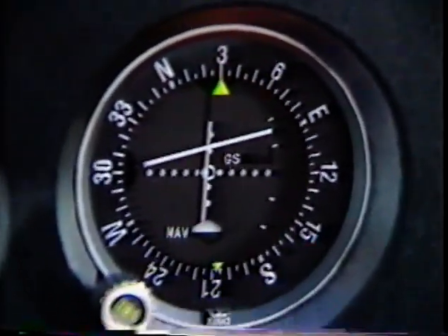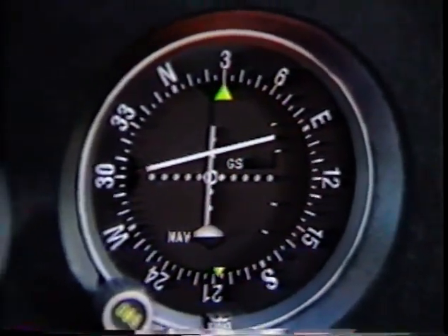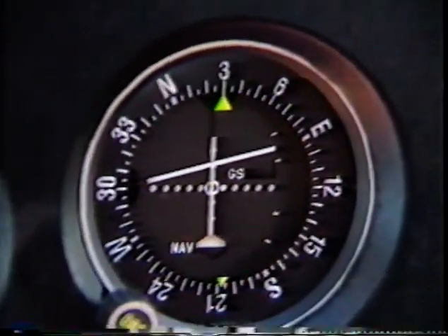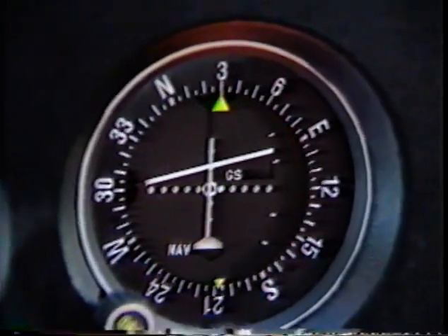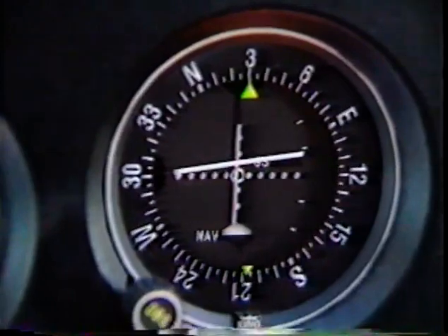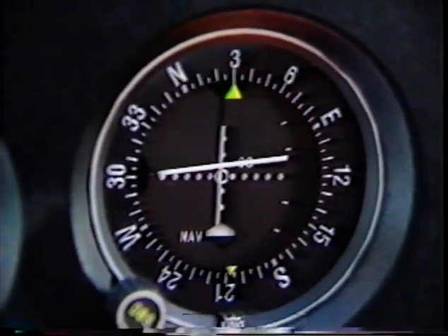On an ILS, the final descent is begun when the glide slope is intercepted, not at the outer marker. Glide slope interception does not usually coincide exactly with marker passage. As the glide slope needle centers, establish your approach descent configuration.